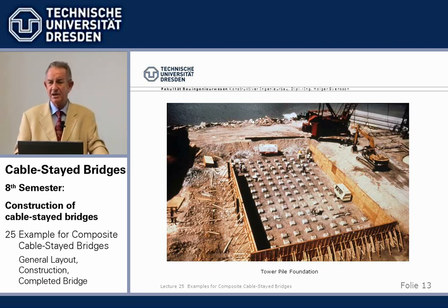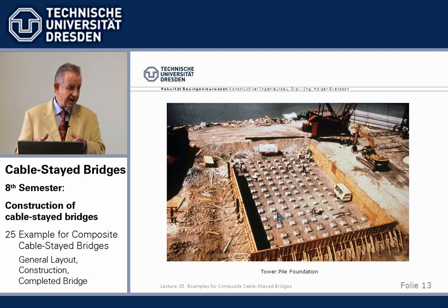So we decided on what we called a floating foundation. We used square concrete piles, 50 by 50 centimeters, post-tensioned, and they were hammered into this alluvial soil, and in a way they were floating there. Naturally, you need a criterion for how much you can put on, and that has to do with the settlement, how much settlement you permit.